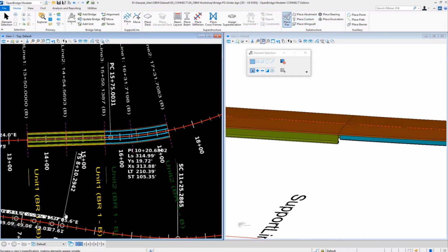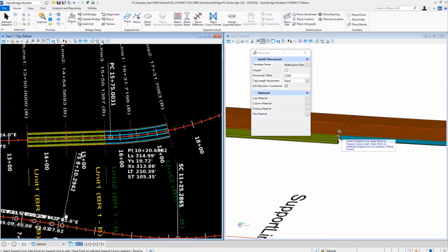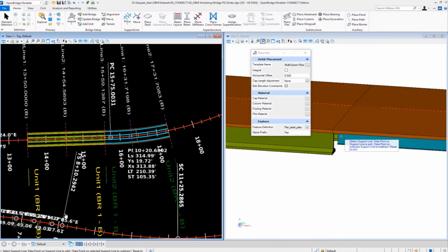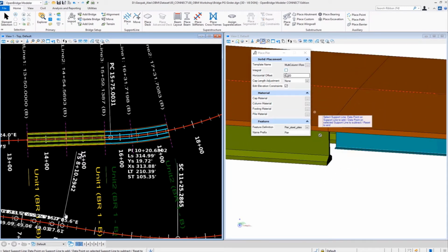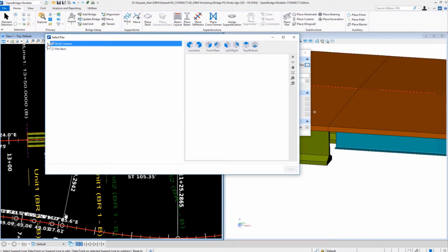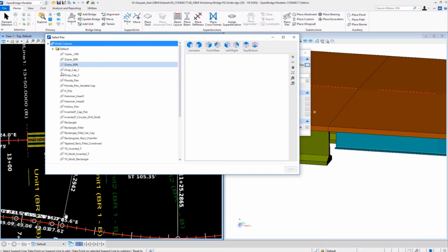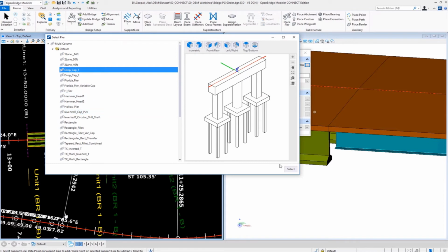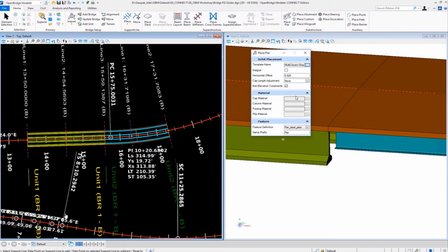So right now, that is the pier command, and then there is nothing special. You just place the pier, and the software will just recognize that it's between two different kinds of bridge units, and it will just place it, in this case, following the lowest one, right? And then you have to do it applying beam seats, right? So place it, adjust them by deck and horizontal offset, and you got the pier there, right?